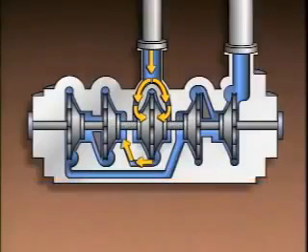From the discharge of the first stage volute, the liquid flows into the 2nd stage suction eye, then out of the 2nd stage discharge and on to the 3rd stage suction eye, and out of the 3rd stage discharge to the suction eye of the 4th stage. The liquid from the 4th stage is routed to the suction eye of the 5th and final stage. After the liquid passes through the 5th stage, it leaves the pump through the discharge piping.